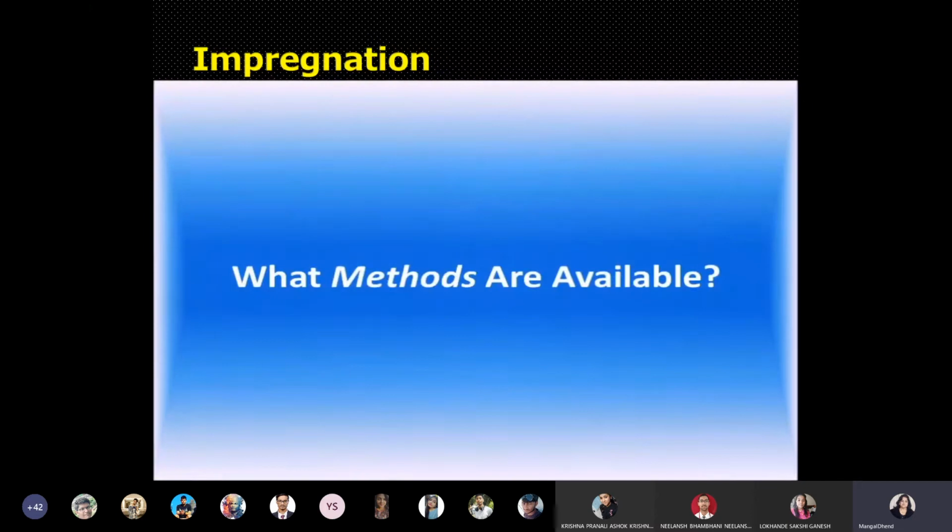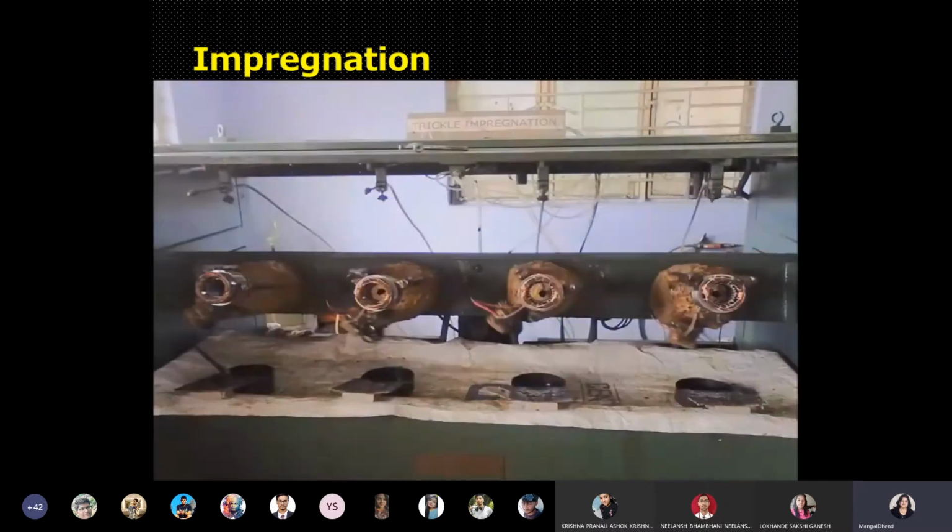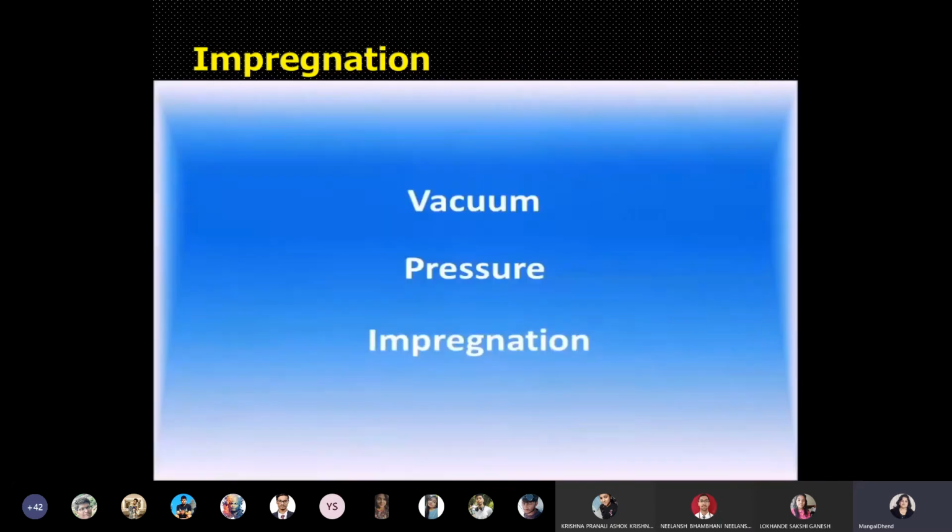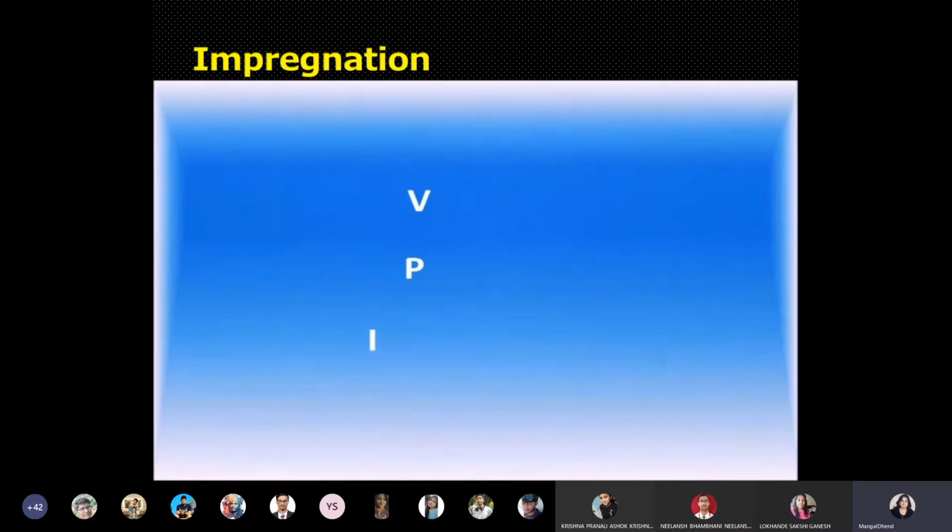Well, there are various impregnation methods available, chosen based on such factors as the voltage of the machines and the cost of the system. For example, many low-voltage manufacturers use hot dipping technology or trickle impregnation. However, for our purposes, we will be discussing a method known as vacuum pressure impregnation, or VPI, which involves the use of a vacuum and pressure, as the name implies, along with a resin instead of the traditional varnish, and is primarily used for high-voltage motors and generators.